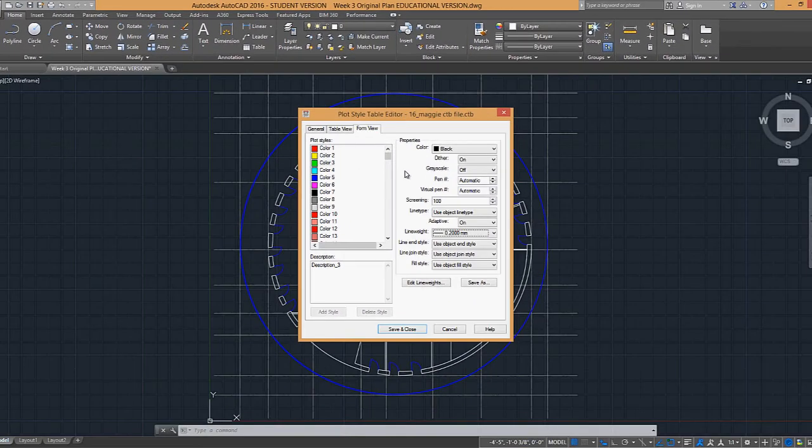Okay, I don't have to hit enter. Saving it is going to save it and close. So I'm just going to keep going down the line. Blue is obviously black because we want a black line for our blue color. And then our line weight is 0.15. Magenta we don't have. Cyan is 0.05. Black 0.05. And then color 8 and color 9, etc., etc. So we're not going to get into that just yet. So I'm going to just save and close it as I have it.